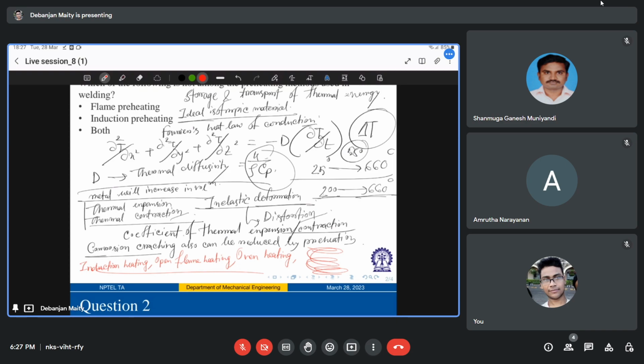So as I was discussing earlier, it is like gas welding, right? Here you are producing a flame through a mixture of gases, burning some gas with oxygen. The operator uses a fuel gas and compressed air torch, and then applies the flame directly to the metal part. That's how it works. And what is the advantage? As you already have a torch, additional equipment does not need to be purchased for preheating, and very little or no operator training is required.